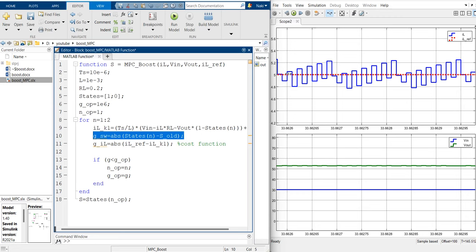In that case, the switching frequency will reduce, because, for example, if the switching state starts here, up to here the switching state cannot be changed. After here, it can change. So it will change depending on the defined value. Now we need the total cost function to minimize the error. We can write the total cost function here.